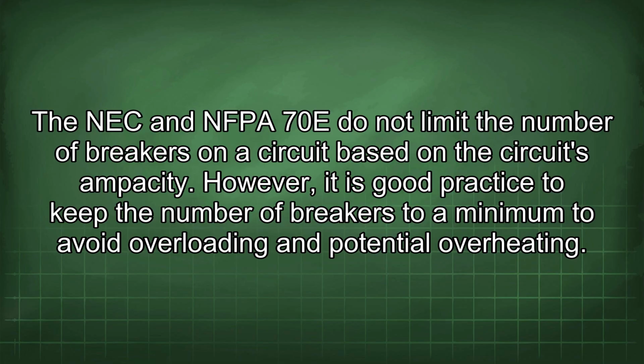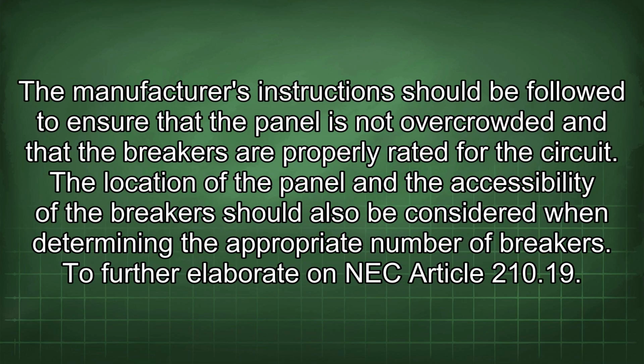The NEC and NFPA 70E do not limit the number of breakers on a circuit based on the circuit's ampacity. However, it is good practice to keep the number of breakers to a minimum to avoid overloading and potential overheating. The manufacturer's instructions should be followed to ensure that the panel is not overcrowded and that the breakers are properly rated for the circuit. The location of the panel and the accessibility of the breakers should also be considered when determining the appropriate number of breakers.